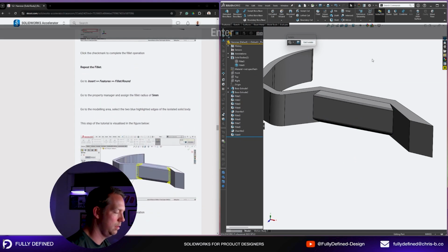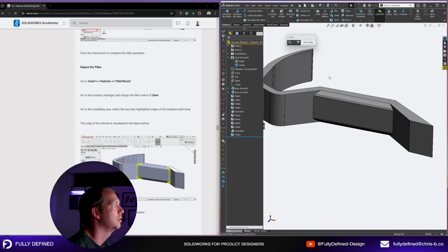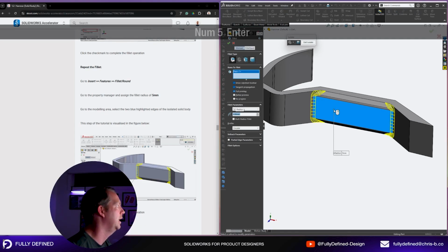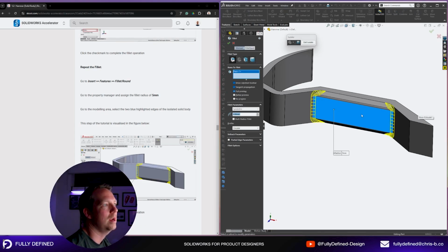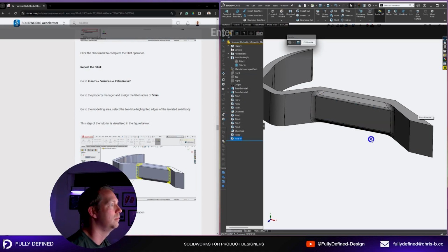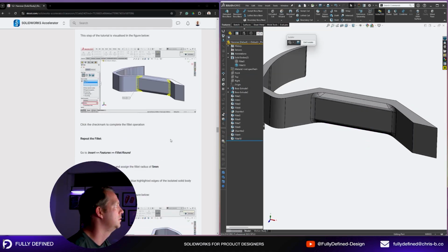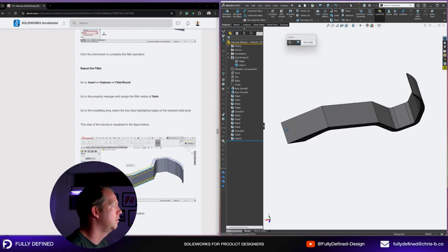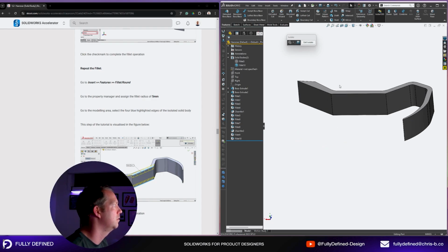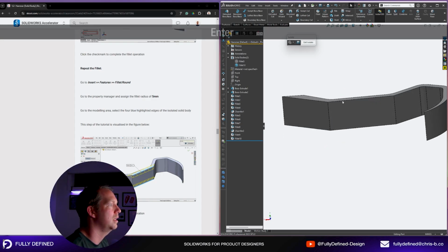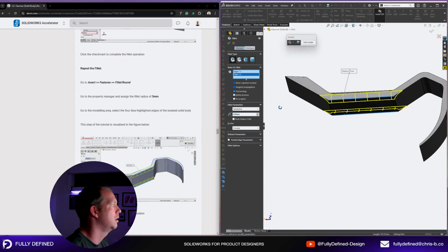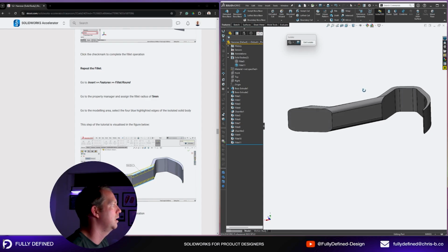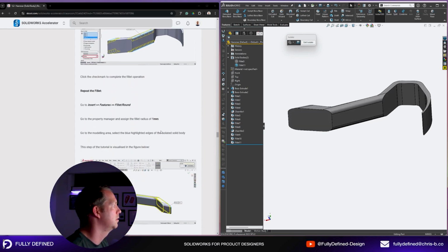Repeat fillet. 5. So again, the example, instead of selecting 2 edges, select 1 face. That'll save us some time. More fillets. So if I rotate the body around, we've got some 5mm radiuses here. Okay, it's looking all right.